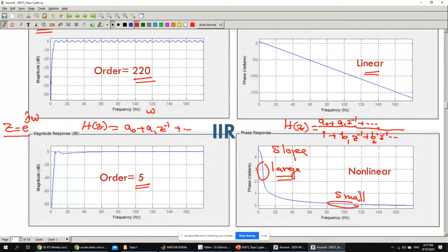Any signal in the world is just a summation of different frequencies, and each one of the components has a different delay. If you enter this signal into a filter, and this filter changes the relative delay between the components of the signal, you might end up having a distortion in your signal. Okay, so a nonlinear delay will be a bad thing.